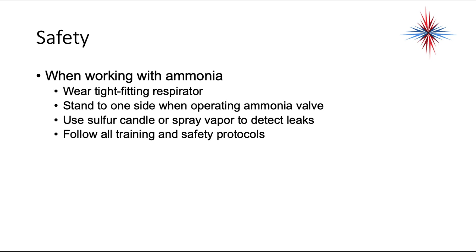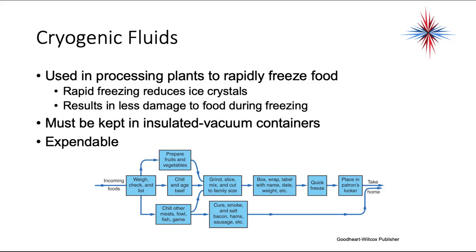You use a sulfur candle or spray vapor to detect leaks. You want to follow all training and safety protocols. You're going to be specially trained if you handle ammonia.